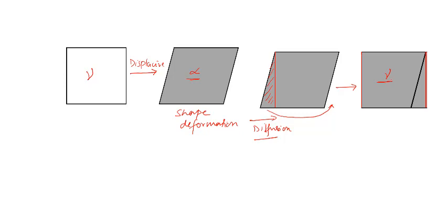right? So that is the implication of diffusionless process, or if you say diffusion is allowed or not allowed. Okay, that's the implication that you can see from here. If diffusion is allowed, this shape deformation would be eliminated by the mass transport.